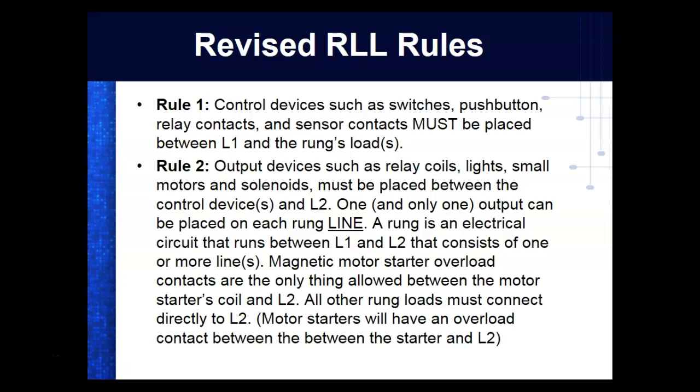Motor starters. The problem we have with motors is that when you start them, they pull about 6 to 8 times what they do when they run. So you have to fuse them for getting them started, right? You understand? So if the motor doesn't start, the fuses are not going to blow, because they're designed to let the motor start, right? You understand?